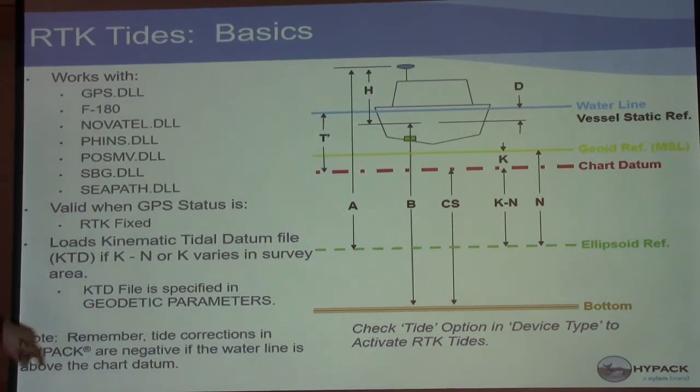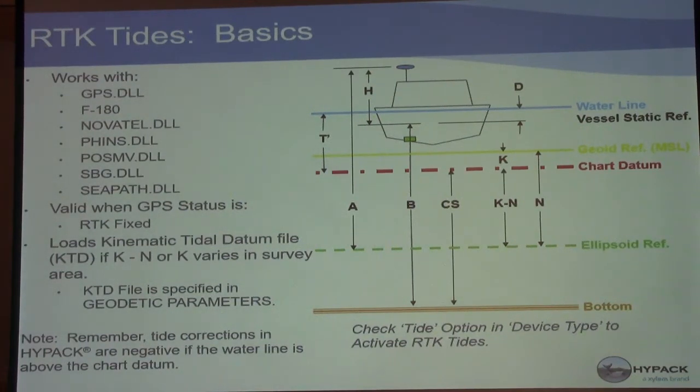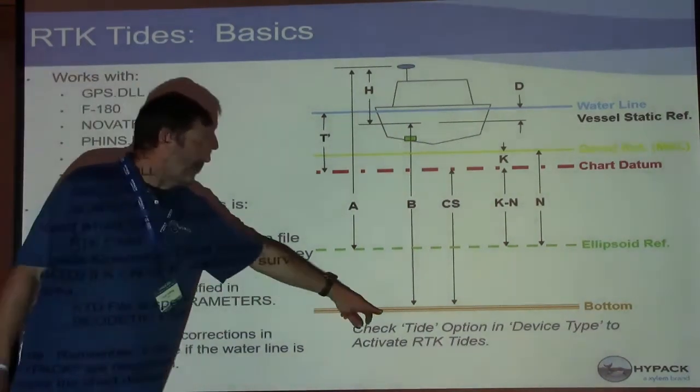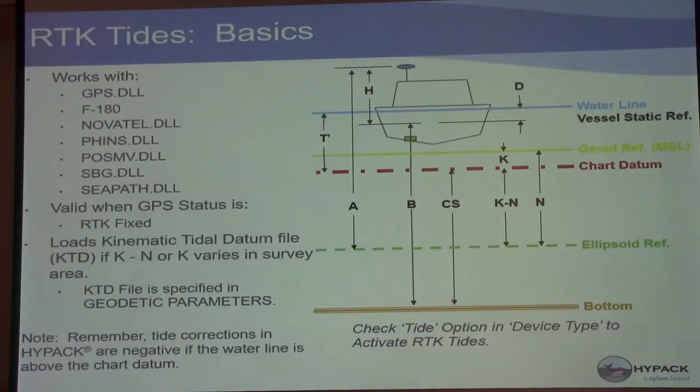Important note here, remember tide corrections in HYPACK are negative if the water line is above chart datum. So again, it's a tide correction, it's not a tide value. It's hard for people to get that ingrained in their heads. But that's just the way it's been in HYPACK for quite a number of years. I don't know if we're going to change that because it might cause more issues, but who knows, maybe if we get general consensus on making the changes, we will. All these device drivers have a tide function in hardware.